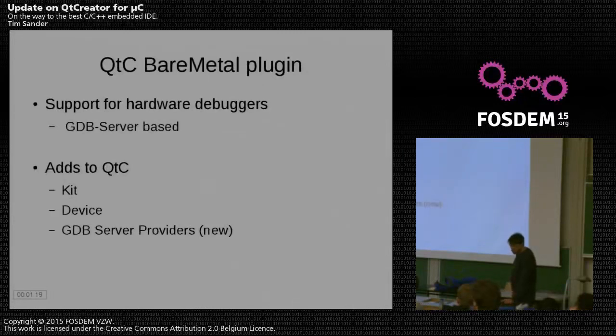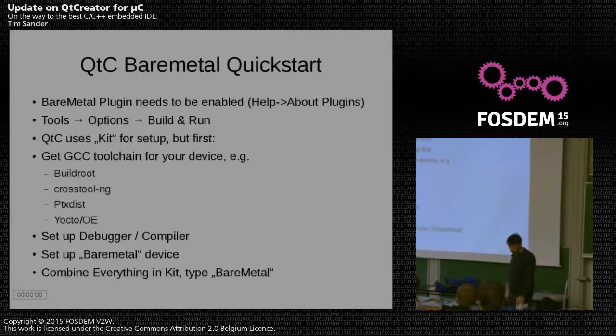And with this kit, you also need a BareMetal device, which has also been added by the BareMetal plugin. And there are now GDB server providers, which I'll talk about later, which make debugging a little bit more comfortable. Okay, I will show that later on in the hands-on. So just this quick start, how you start BareMetal debugging, and it's pretty quick and pretty comfortable.